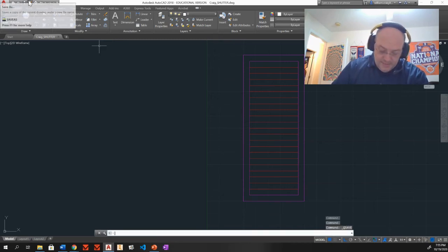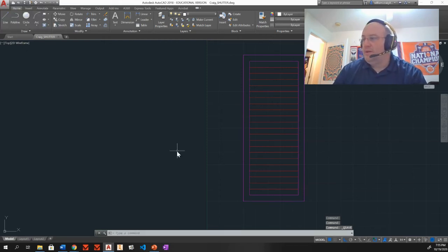All right, step 6. It says to O snap a line out, or a layout line, from midpoint side to midpoint side. What we're talking about here, and we're going to be deleting this line later, is we're trying to find the midpoint of the shutter. So as I come down here, you see that little green triangle showing up right there? That's where I want to snap to. So I'm going to click there. I'm going to come all the way across, and you see the other triangle. That's what I want. Select that, press escape, and I have this little guideline that I can work off of.